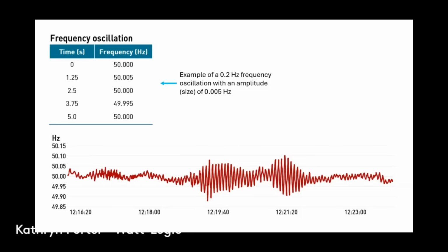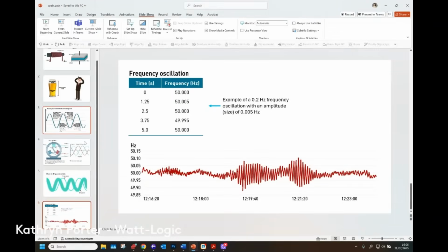So effectively, this 0.6 hertz frequency oscillation that had an associated voltage oscillation and voltage drop was the cause of the Iberian blackout. But that's a little bit too crude an analogy, because fundamentally so many things didn't comply with their grid code obligations that it was almost inevitable that the grid wouldn't be able to cope. So the key messages that we can take away from this report, I'll put myself back on camera for this.